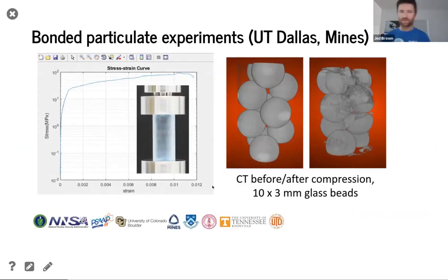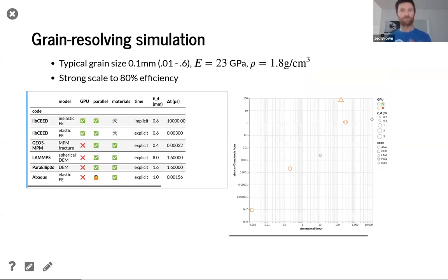So an example of the kind of experiment, this is the first year of the project, so things are greatly simplified, but it will have, say, a cylinder with a bunch of beads and epoxy, and these get crushed in the lab. We get measurements of stress and strain. And from that, we want to infer properties of these materials as a composite. And things are going to get a lot messier in the coming years because these aren't going to be spheres anymore. They're going to be these angular crystals with a really big size distribution. There will be little pores where the binder doesn't fill in completely. But we take these kinds of experiments, which have CT scans from before and after, and then we want to put together what were the materials in there. And now let's make predictions in more complicated settings where we can't create that simulation.